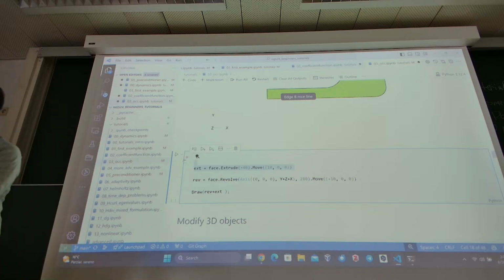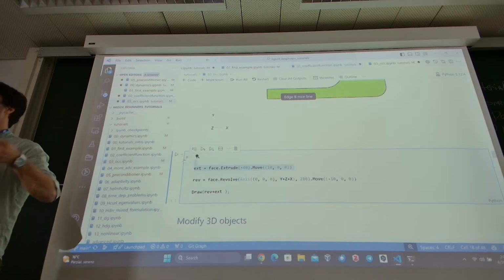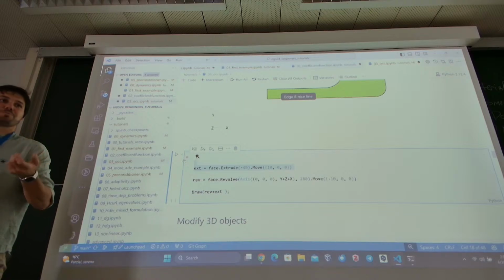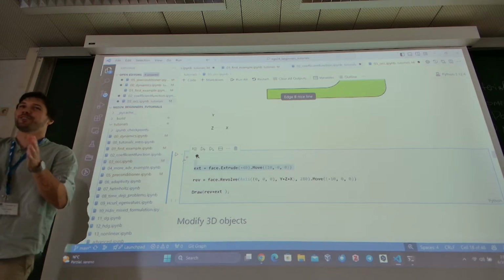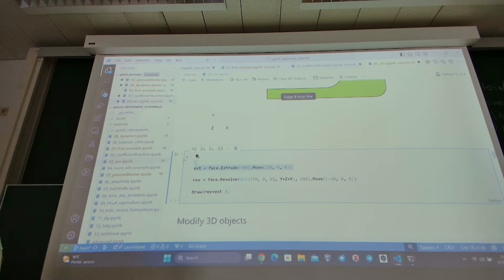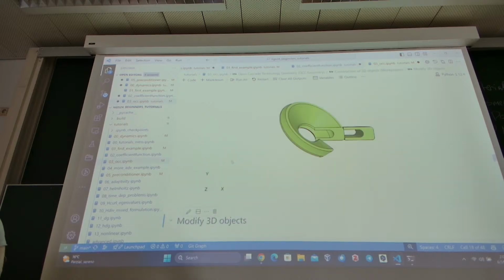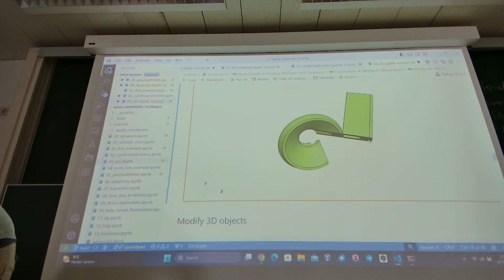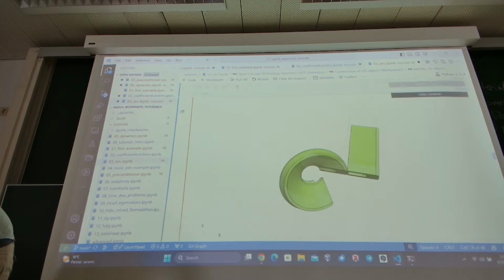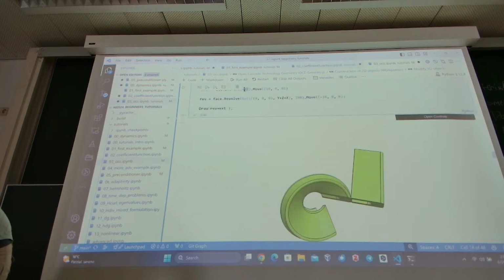So if you name a surface, I don't know, surface Edoardo, then the whole volume at the end is going to be called the volume Edoardo. Right. So let's play with it, or let's try to extrude it. The extrusion is going to be in a certain direction, so you can specify the direction. At this point, say, okay, -40 as magnitude, and it's fine.